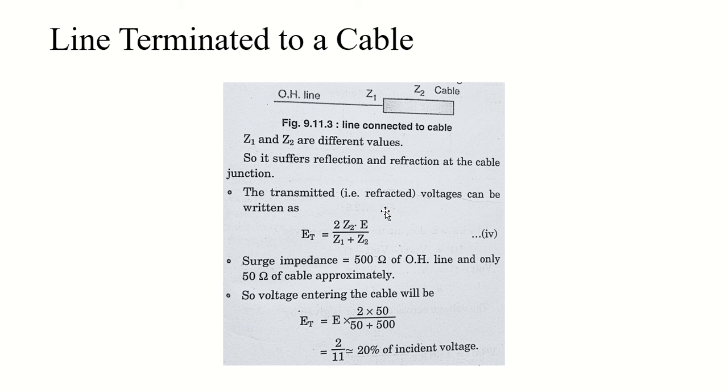Also it reduces the steepness of my wave, right? It will make it less steep and more balanced, right? When we reduce the steepness, then we reduce the voltage distribution along the equipment winding, right? It makes my voltage smoother.